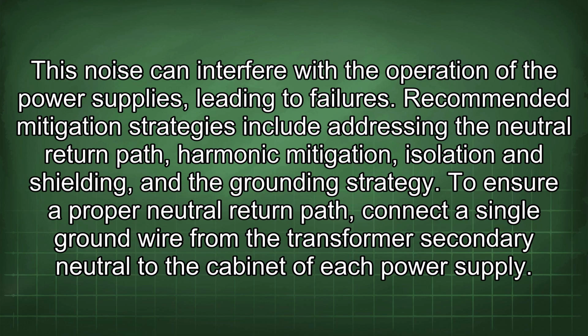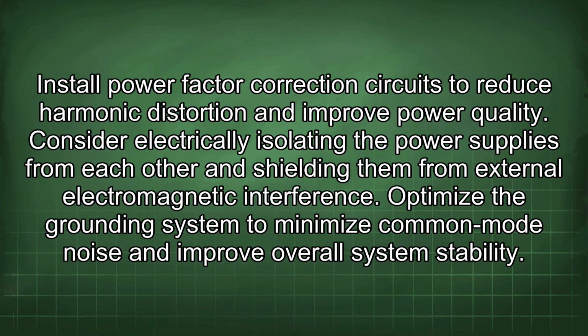of each power supply. Install power factor correction circuits to reduce harmonic distortion and improve power quality. Consider electrically isolating the power supplies from each other and shielding them from external electromagnetic interference. Optimize the grounding system to minimize common mode noise and improve overall system stability.